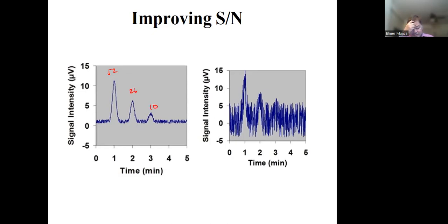Okay. And if you look at the peak-to-peak noise level, that's around 0.19. Now, what happens if you make this 10 times? So this now becomes 1.9. And if you have that 1.9, what will happen here to the signal-to-noise? So you increase the noise by 10, so your signal-to-noise will decrease by 10.